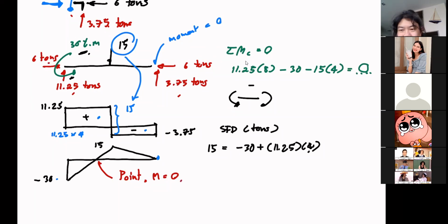So, if we cannot build one long member and we need to connect pieces of a structure to form one long member, this is where we want to connect: the location where moment is equal to 0. We call this point of inflection. Okay. Now, if there is any point of inflection in your bending moment diagram, you should always locate it.